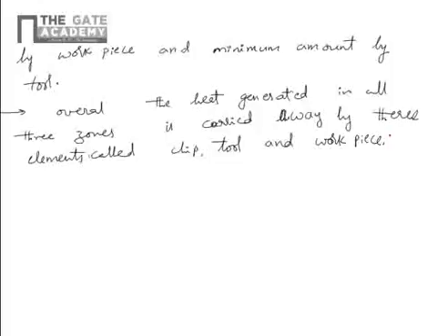If the convection and radiation losses are negligible, the chip carries away the maximum amount of heat. Next is the workpiece, and the least is the tool, because we are neglecting the radiation losses.